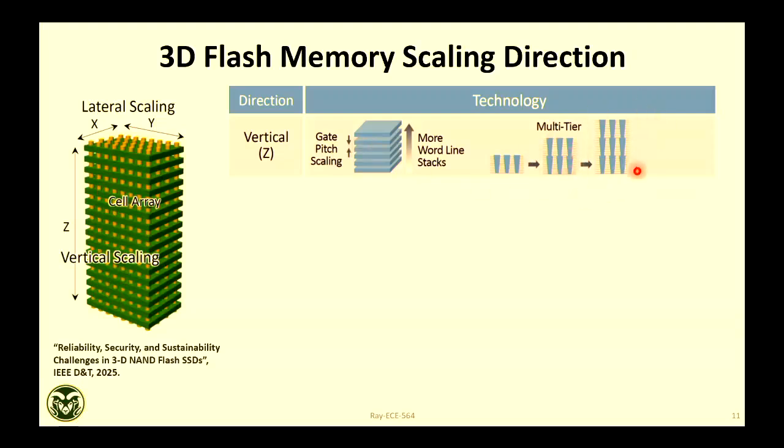Another technique the industry is now taking, which is very interesting, is going into multiple decks or multiple tiers. Suppose this is your 100:1. You grow 100 layers, and then you make an interface in between, and then again you start growing, right? It's called multi-tier processing. You finish one deck where 100 layers are grown, and you can see there is a tapering shape, and then the same process is repeated. Only thing is your thermal budget will be a little bit limited for the top tier.